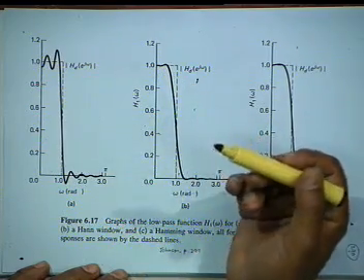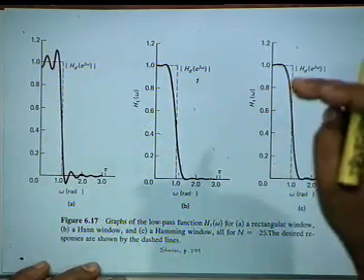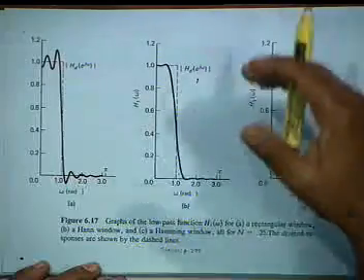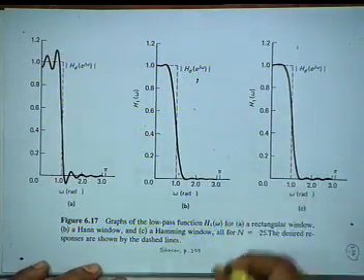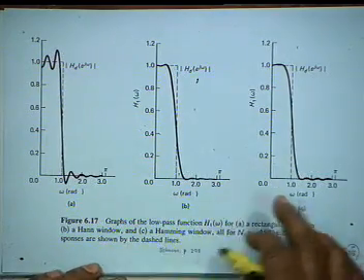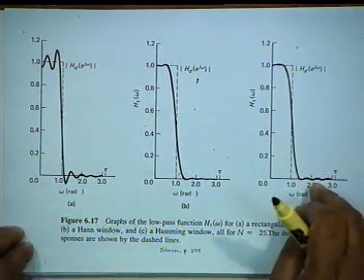In FIR design, conventionally, traditionally, the pass band is specified as 1 plus delta 1 to 1 minus delta 1. If you want to compare with our adopted philosophy as we adopted in IIR design, you will have to convert them. So, I would suggest that you make normalization with respect to 1, then you find out what is delta p and what is delta s. So, obviously, this design is much better, is the best of the three. But if it satisfies the specification, then you accept that.